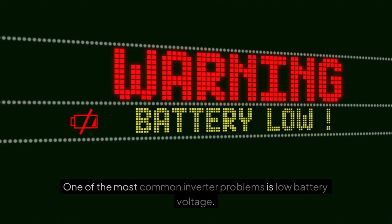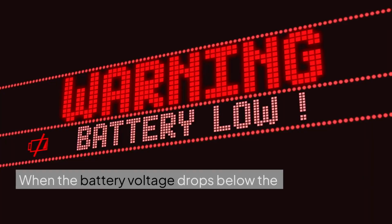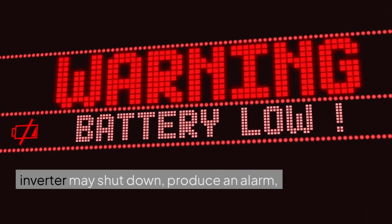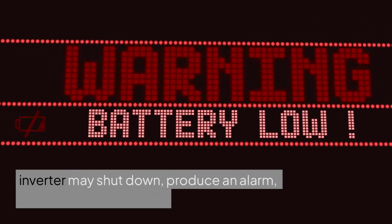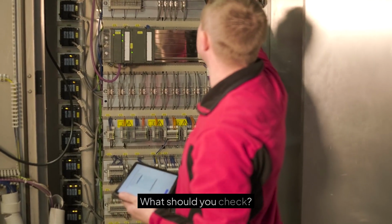Let's get started. 1. Low battery voltage. One of the most common inverter problems is low battery voltage. When the battery voltage drops below the inverter's acceptable operating range, the inverter may shut down, produce an alarm, or disconnect the loads. What should you check?